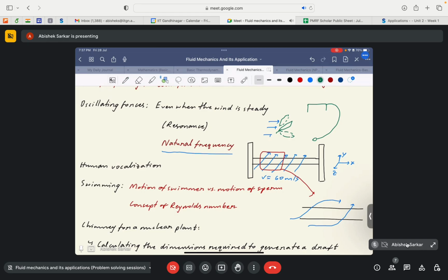That is, if initially the displacement was very small, and the frequency of oscillations due to this external force matches the natural frequency of the deck, it will result in very violent oscillations from its main position, which would thus result in the failure of the bridge. And that is exactly what happened in that case.